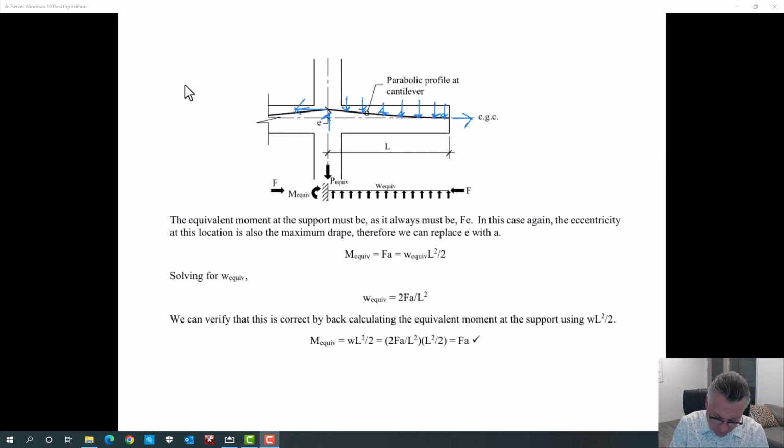There must be an upward load. So this is keeping the tendon in place, some uniform load. And remember, anytime you have a parabola, you have a constant uniform load. I kind of derived that a little earlier. Placed on the concrete is all of that in reverse.